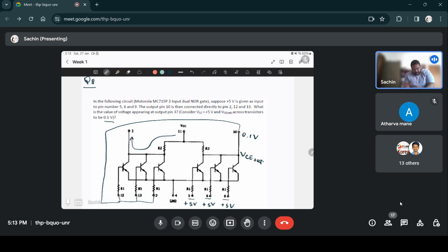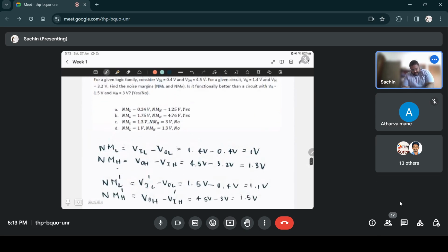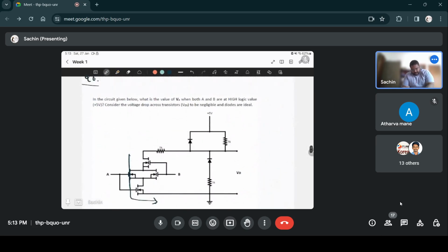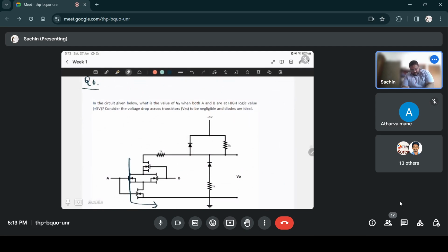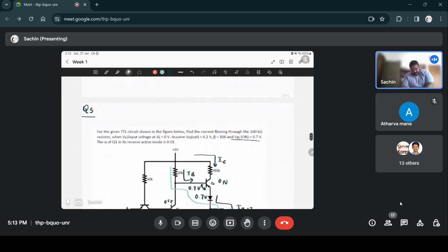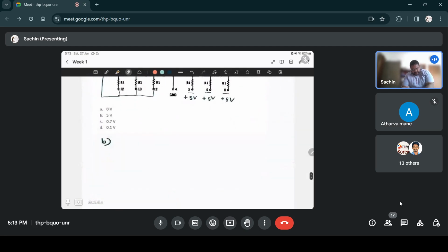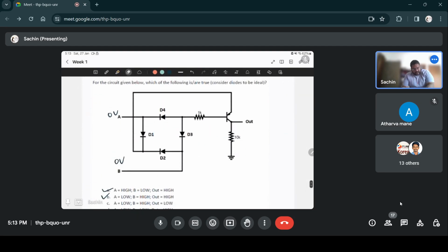This will be inside a chip, all these transistors, and you have to connect that pin number 11 to an external power supply. Similarly in other circuits also. So there's a plus 5 volts here. The plus 5 volts is something you supply. If nothing is supplied in the circuit, it's just a bunch of wires hanging about, and there's no potential difference. So magically there can't be a potential difference anywhere. Everywhere it will be 0 volts.